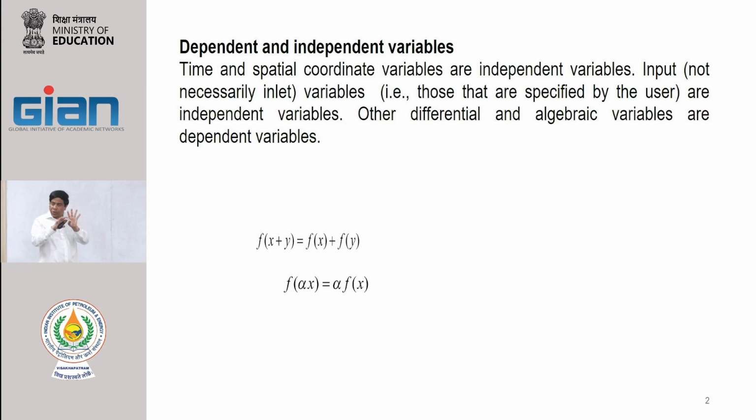You have done those degrees of freedom analyses, but sometimes this becomes confusing when you are using software like Aspen where some models have been built. If you are the one writing the equations, you probably count: okay, these are fixed variables, these are free variables, and this I must fix to make the degrees of freedom equal to 0, and that's how you go.